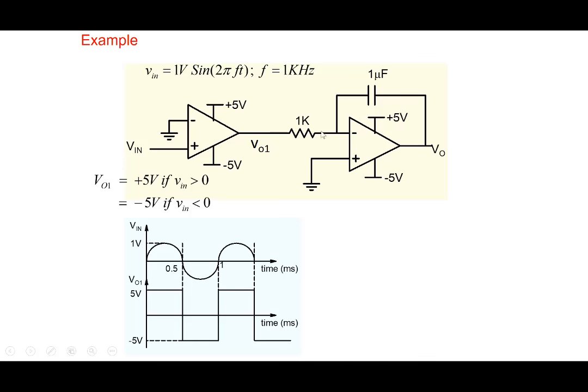And so we've taken a sinusoid and converted it into a square wave. The square wave is being fed into an integrator, so what we'll get is a triangular wave. So you can see a waveform converter circuit here. You can go from sinusoid to square to a triangular waveform. All right, so there are many other useful applications of op-amp circuits, and that's why this block is named operational amplifiers. You can add and subtract, you can take log, you can take anti-log, you can differentiate, you can integrate, and you can even solve differential equations. Okay, so let's stop here.